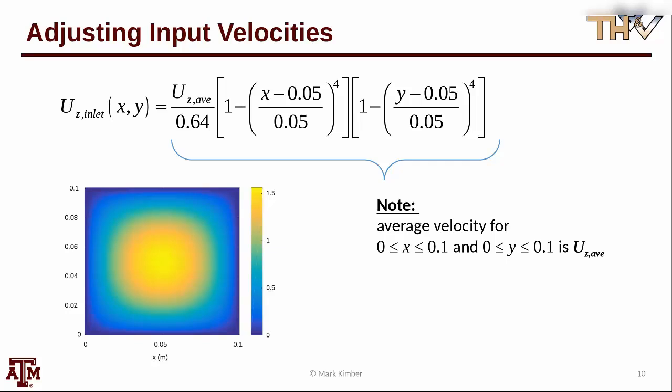Because in reality we need to take the discrete values, the x and y values there, and then evaluate a function that describes our profile at those discrete locations, or we need to take experimental data, which undoubtedly is going to be measured at different intervals and at different locations than the XY locations that we happen to have for all of our cells. So we need to be able to take that and interpolate that to the base X and Y locations that represent our inlet cells.